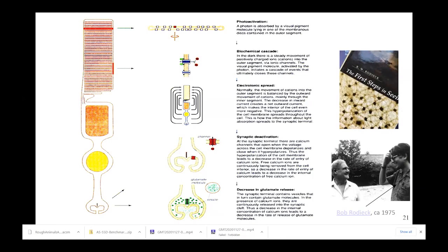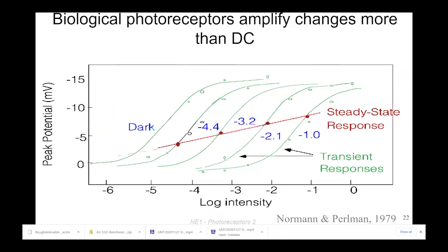But I'll just say that what we tried to capture in the electronic photoreceptors, for many years, was this adaptation property. You get a low gain for DC and a high gain for AC. In other words, you should amplify the changes, which are presumably more interesting than just the static, boring stuff that's sticking around. It's a general principle of the nervous system, extending from every sensory input all the way through the computation that's happening in synapses, in cortex.